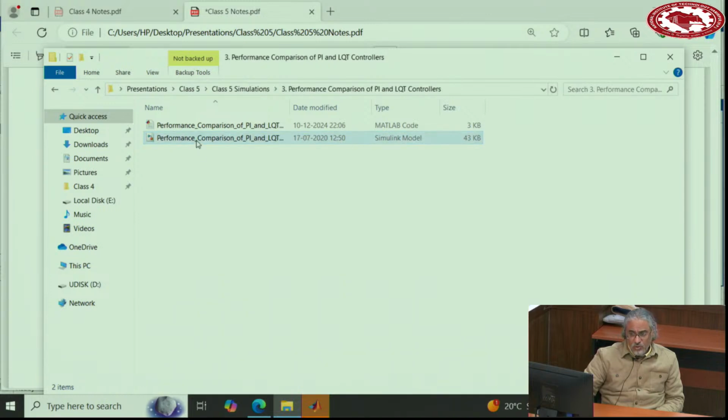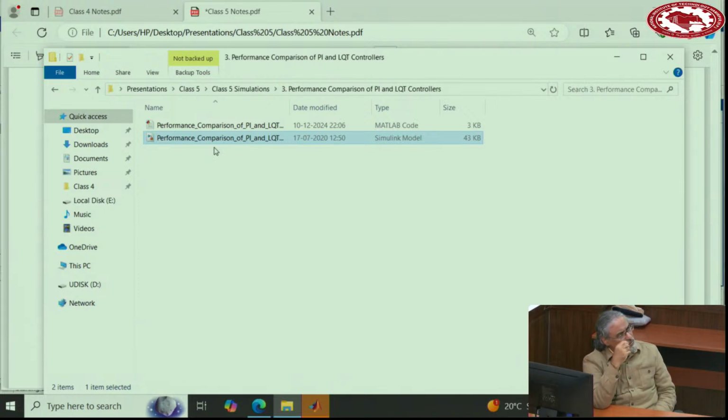Yeah, you need to select that low pass filter properly. Again, the design of that low pass filter. Remember, why do we put that low pass filter? To help the current limiting, right? And remember, this is outside the loop, not inside the feedback loop. If it is inside the feedback loop, yes. Now, this is outside the feedback loop. If you put too much delay in that low pass filter, it does not help a lot, because when the grid voltage drops, you want it to come quickly to the control system.